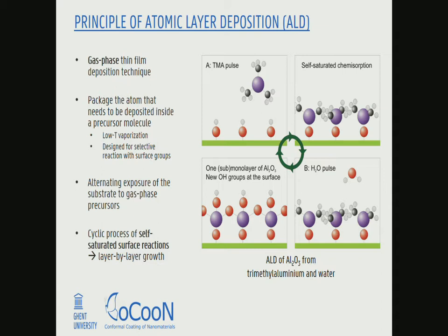That's the basic idea. Now, after this first step, you've been very successful at depositing a single monolayer, or usually a sub-monolayer. But if you're really honest about it, you haven't deposited aluminum, you haven't even deposited aluminum oxide, you have deposited some aluminum atoms with still a lot of ligands.